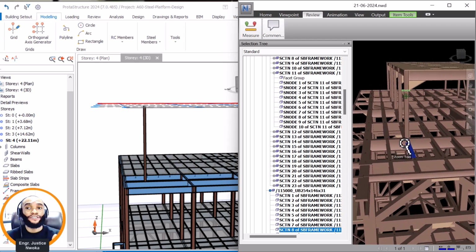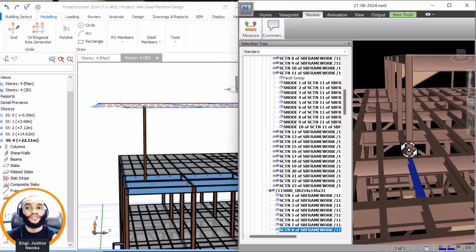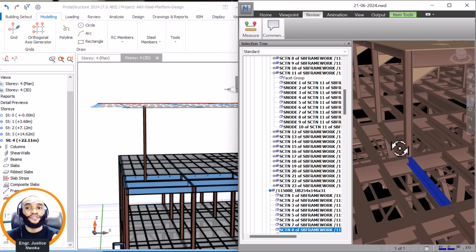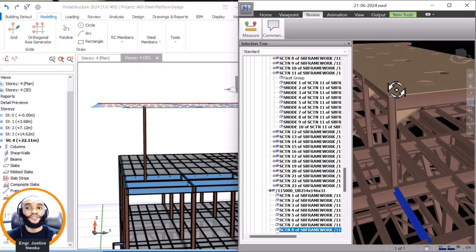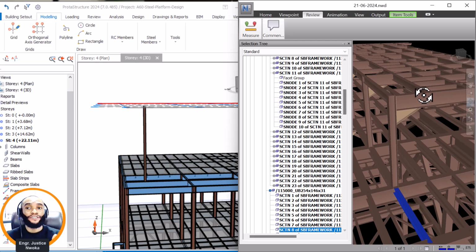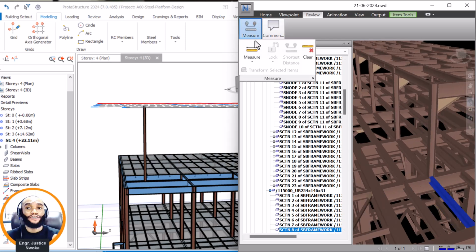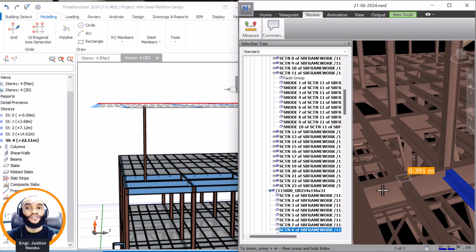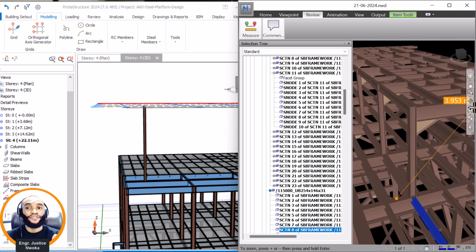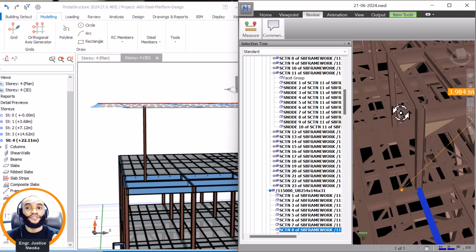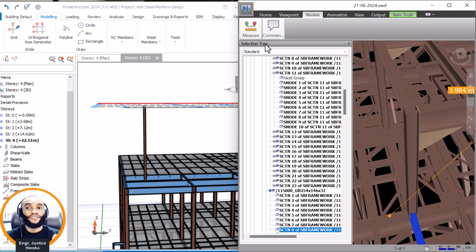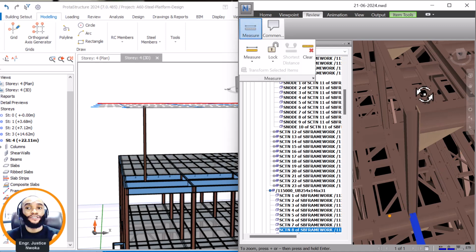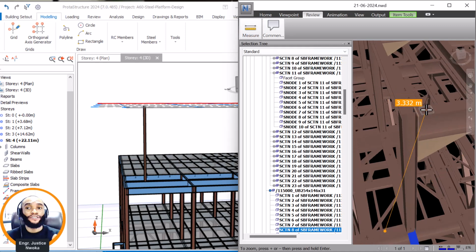So by doing that, now we're going to do what? Measure. Okay, measure that. Top of steel to top of steel. So with that, I'm going to remove this grating here to get the actual top of steel. Measure from here, top of steel, measure from here, steel top, then come again here, then rotate again, measure to this other steel top here. All right, measure here, that's fine. This steel top here too, that's fine.